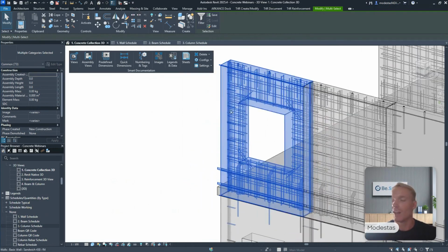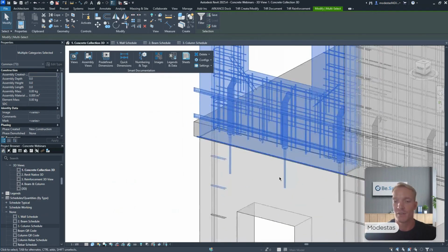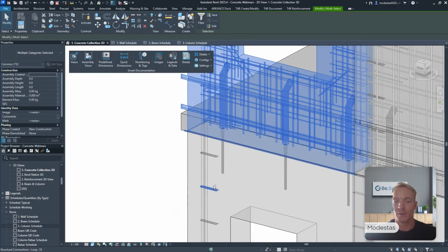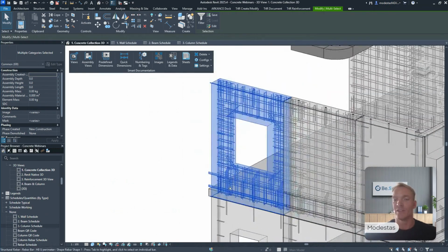I selected all these elements that I want to create an assembly of, and I see that I have 4 elements selected from the panel that is beneath it, meaning that I would get some elements that should not be in there. And if I have a lot of other elements surrounding that panel, it would be extremely hard for me to get a correct result. So once you selected all the elements, just like that, you can go ahead and use Create Assembly.